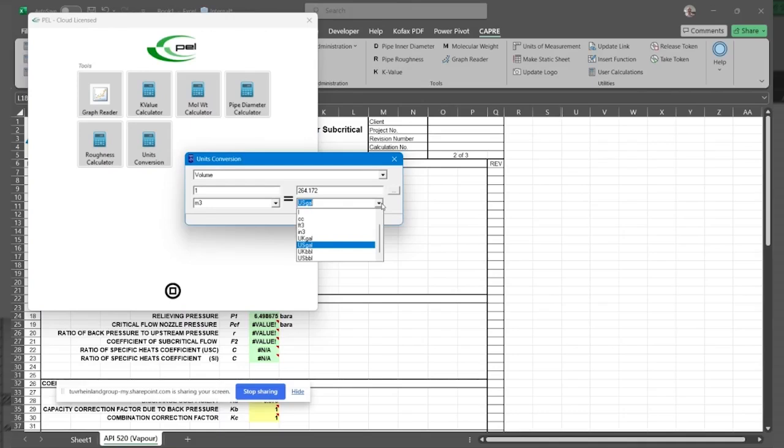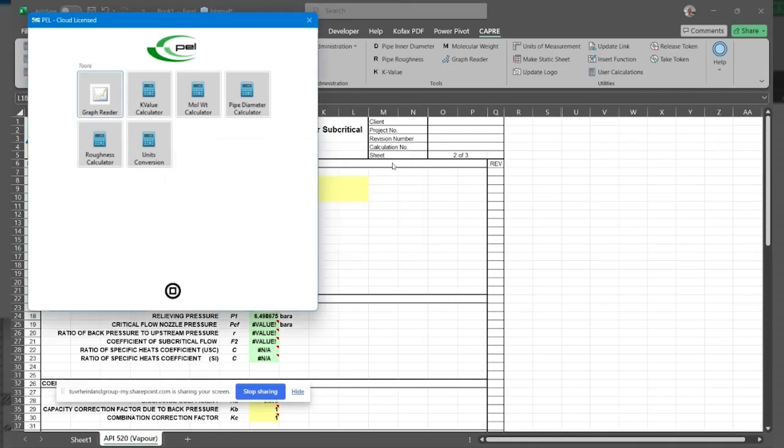Not all of them will be there, but it'll give you a good idea of what units you can put in. So if you are in gallons, or maybe you want US barrels, so US BBL, you can find it, and then you can write that into your unit set. So it's a way of finding out that unit list relatively easily, or a good starting point at least.